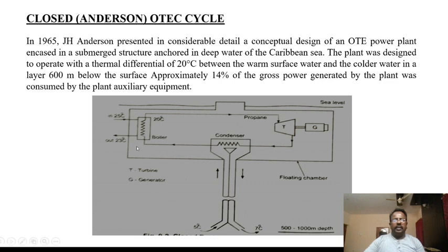The working fluid in this system will be different. It may be an organic fluid, ammonia, propane, or freon, depending upon the situation. Here we are using propane as the working fluid. The saturation temperature of propane is less than 20 degrees centigrade, so the available warm water at nearly 25 degrees is enough for boiling the propane.